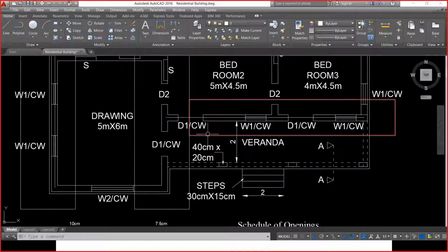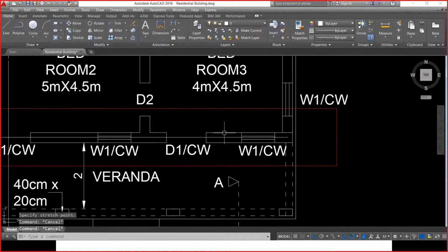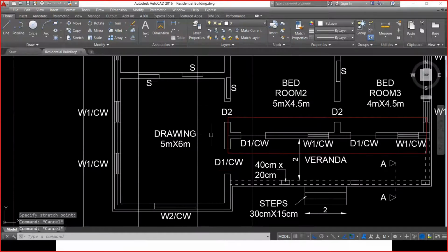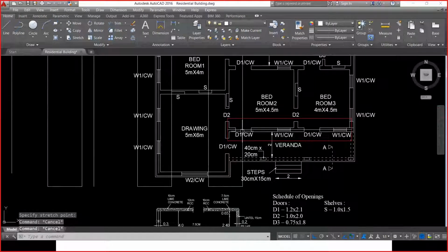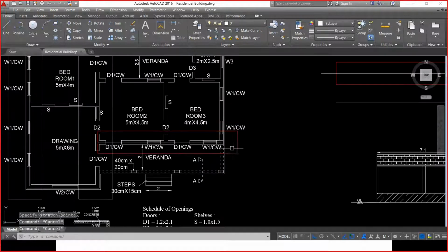The concept remains the same. Even here, let's say the total width is 0.5 meter. This is trying to overlap this. If I consider the center to center distance, the center line will give me only this much area, but I don't want this area because this area is already done. This area is already constructed, and I'm not going to stop exactly here. So this will be the actual width of the footing.